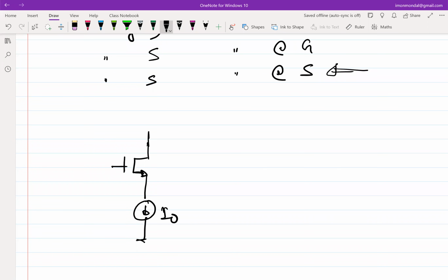So I will look into this voltage, the source voltage. And why am I looking into the source voltage? Because at the end of the day, I know there is this current. This is a voltage control current source. Transistor is a voltage control current source. Once biased in whatever fashion, it will be providing me some current ID. And the purpose of negative feedback is to ensure that ID equals I naught. So I have to do something to ensure that ID is equal to I naught.